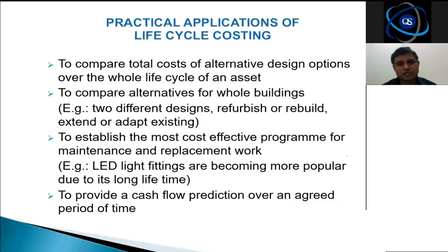One of the reasons is the maintenance cost. In the Muscat area, I haven't seen that much of a problem. But if you are going to the desert area, where there is sandstone, where there are undeveloped areas, you will have to clean this particular solar panel very frequently. Therefore, the performance will go down if you do not do it properly.